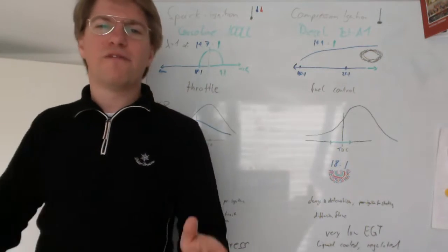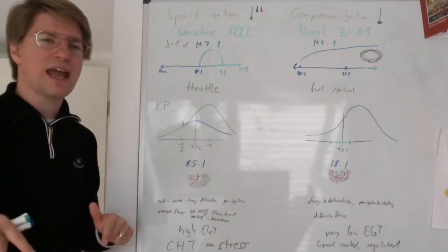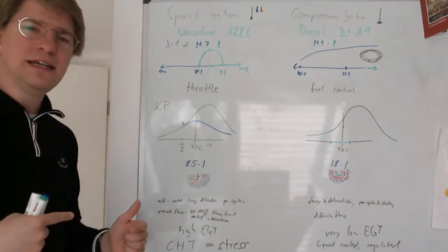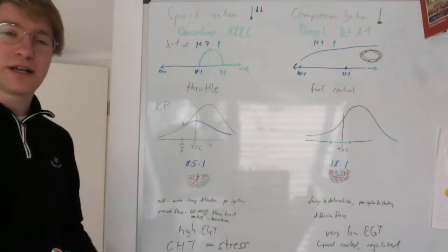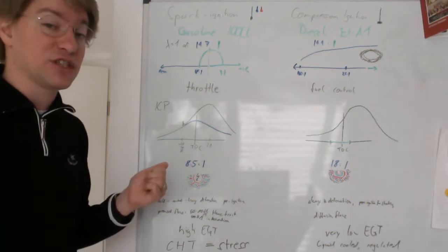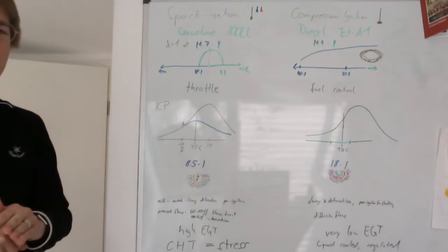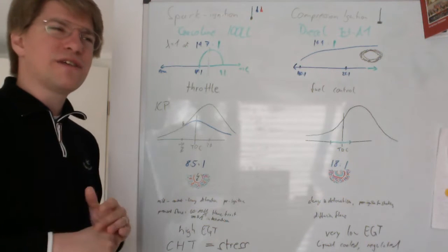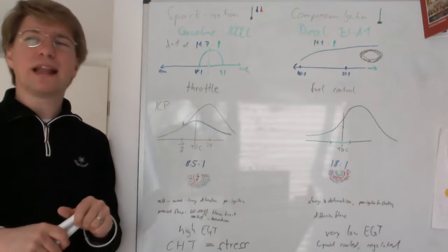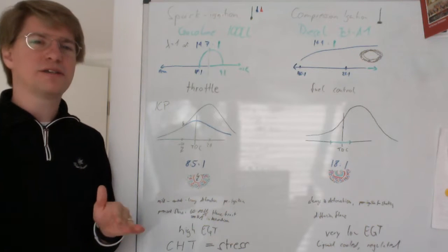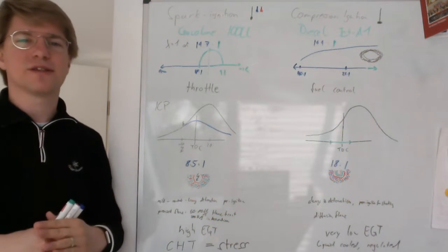What we call the volumetric efficiency of the engine is less than ideal at anything but full throttle, because we are not sucking as efficiently as we could. So running the piston engine at anything but full throttle is not really efficient, which is why we like to cruise at high altitudes, well, assuming the winds are the same.